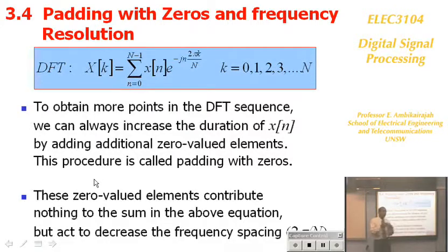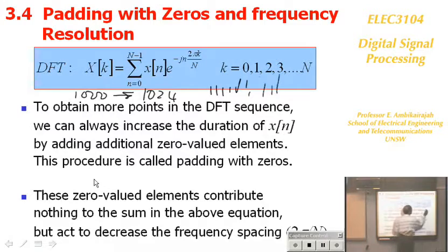If you go for DFT, it takes a long time to process. So people said, if you have a shorter sample, to make 1024 when you only have 1000 samples, these are your 1000 values, you put 24 zeros at the end.